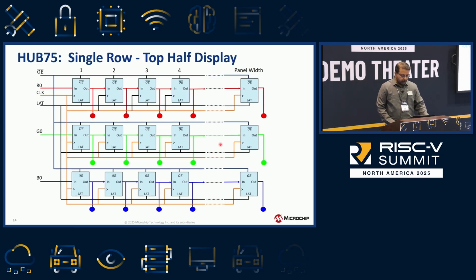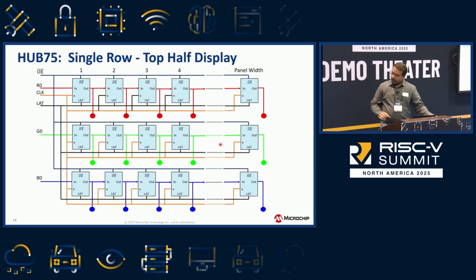Okay, so the entire display is actually kind of implemented like a shift register. What you see on top, these are the red line, the green line, and blue line, and these are all individual shift registers that control the data. So you send your RGB information in parallel, and then you send in your clocks, and your data gets shifted across the LED panel.